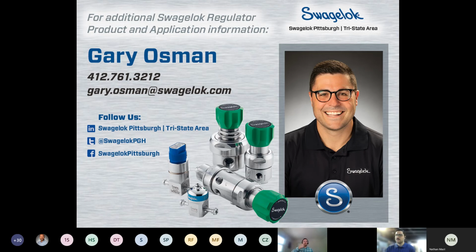That comes back to the regulator and goes into the dome chamber. Now, unlike a typical dome-loaded regulator, differential pressure regulators also have a spring. So the set point becomes whatever's in the dome, whatever you've referenced, plus any additional pressure you've dialed in with that spring. As the system pressure goes up and down, the set point will also change along with it. So it's a different type of pressure reducing regulator that's enabled to reference a portion of the system or a different system anywhere that you want to reference.